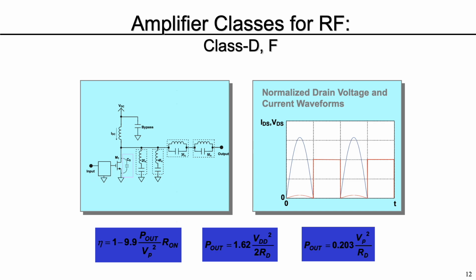Now, the class F amplifier. The idea of a class F amplifier is that, in this example, and again this is conceptual, the way it's shown, there's a bunch of series LC branches in shunt and a bunch of parallel LC branches in series. So the series LC branches in shunt, like the ones labeled 2F0 and 4F0, are going to be short-circuited, or have a very low impedance, at those frequencies. So at the second and fourth harmonic, you're short-circuiting.